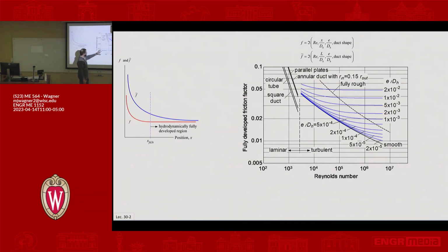So in the laminar region, the things that are important are geometry. And why is that? Because the geometry affects how the boundary layers grow, how they come together. Turbulent flow does not care beyond a few widths beyond the viscous sublayer what's going on. It doesn't care if you have a circular duct or square duct or whatever.